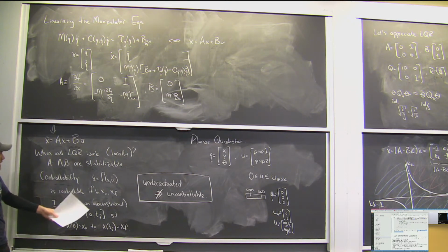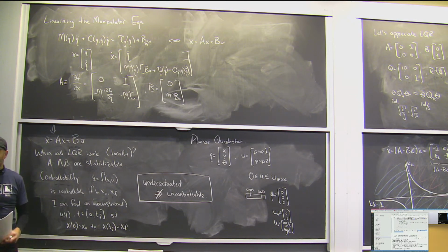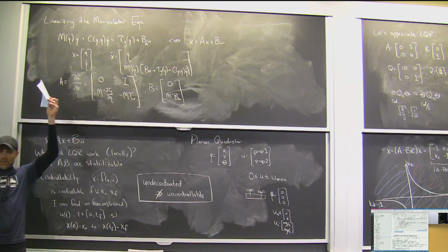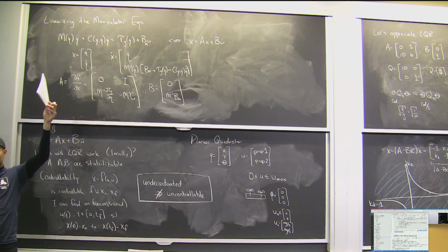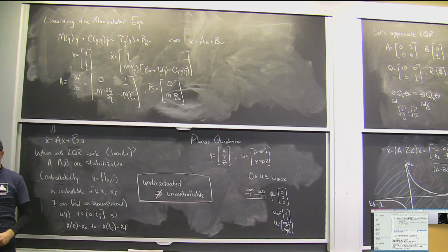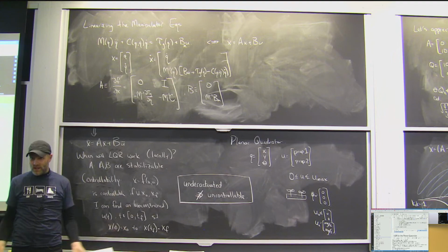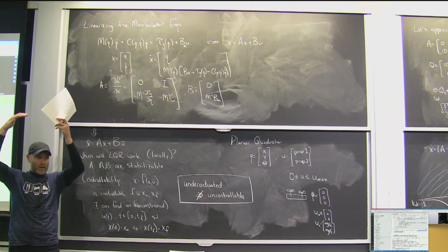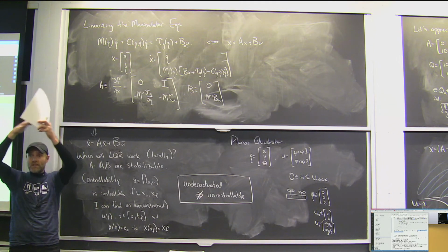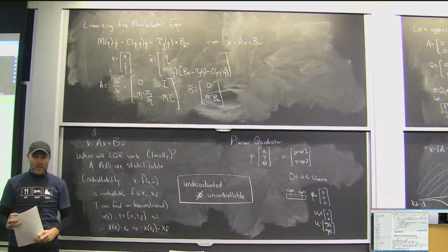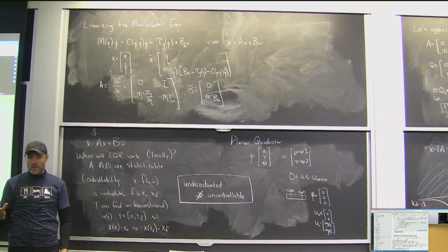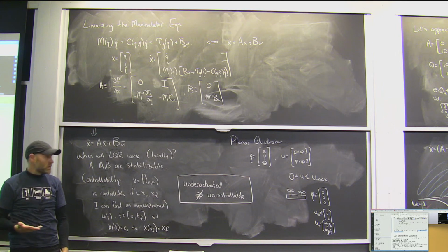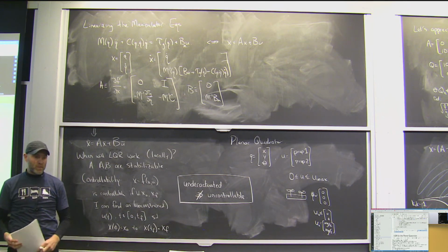But LQR is a pretty darn good tool. It only solves the balancing part of the problem for today. When we're in the vicinity where the linearization works well, this is an awesome tool. We'd like to think that if we're solving value iteration over the whole space, the solution at the top would look like the LQR solution. In the vicinity of that linearization, it's a good characteristic of the optimal cost-to-go. Okay, but we're going to deal with the rest of the swing-up problem next time.